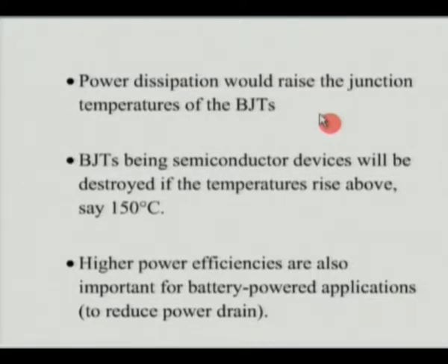One is it is very difficult to dissipate the power and to keep the temperature down, and I am sure all of us are familiar with this if you visit, let us say, a small mobile transmitting station or any electronic application where you have a large amount of power, you will always see a huge amount of cooling being done through fans and so on. Sometimes they would even use coolants to do that. So that is one concern, to dissipate the power.